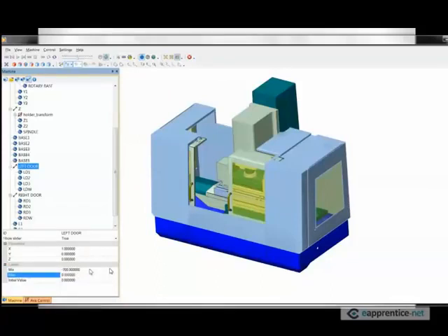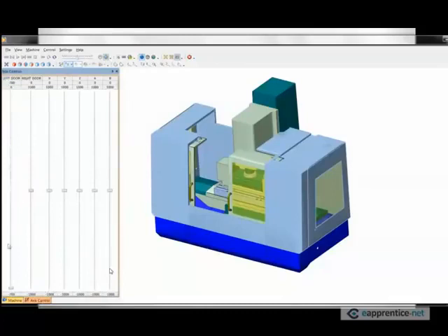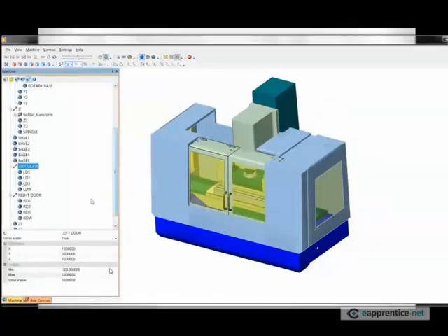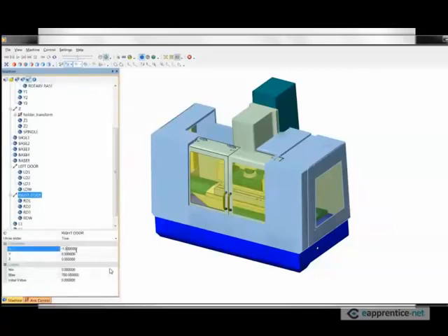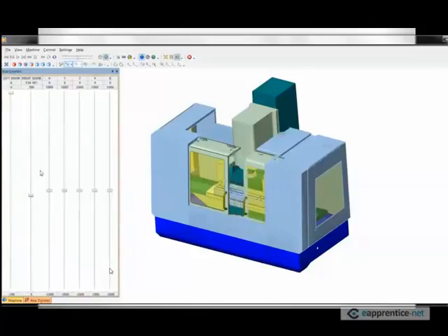By setting that, if I go back now to axis control and move my door, you can see that it's moving within those limits that I set. And this is true for every axis. So you have to go through the whole machine and set your limits for X, Y, Z, A, B, C, whatever axes you have available on this one. So this will probably be 0 to 700. Let's move it around. Oh, but I changed the direction, so I have to change the direction back to move the same way. So I will say the direction is the same, but my limits are between 0 and 700. So now this door is moving that way.